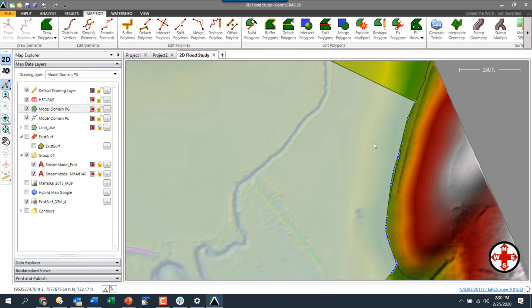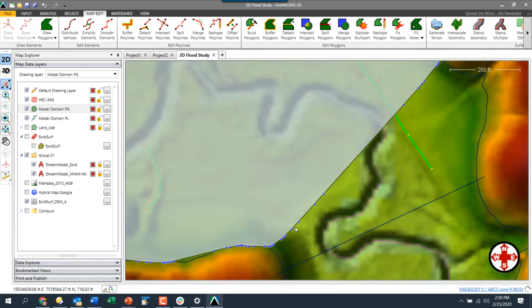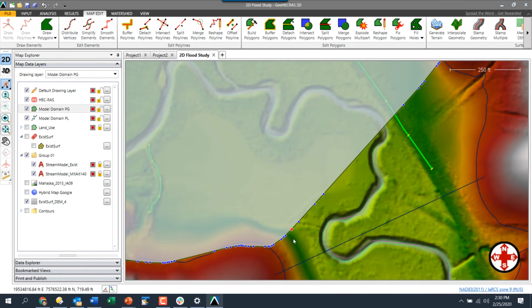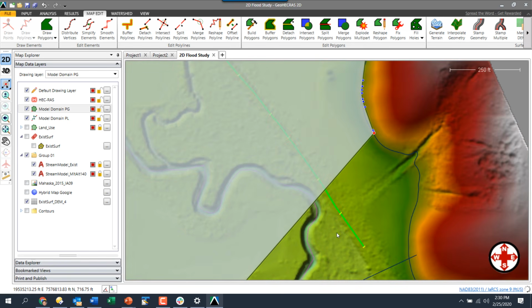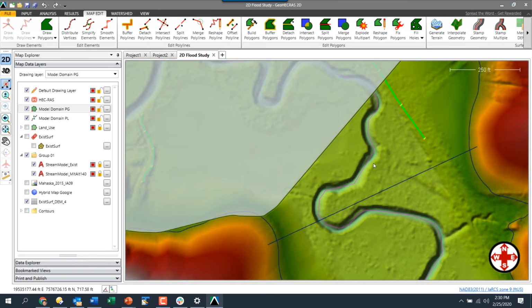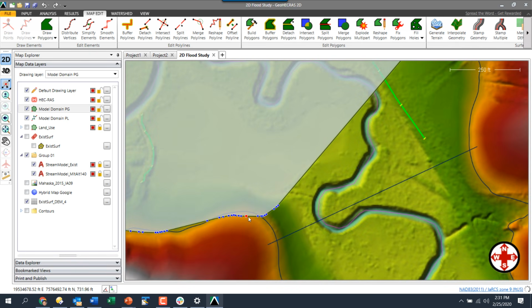There, okay, that one's cleaned up. Same thing along this boundary, come in here, grab one of them, hit the delete key, take it over there, and straighten that out. Oops, and we can undo, Control Z will undo. The same thing, we can come over here, figure out we're going to start deleting there, and trim that out. There we go, and can grab that point, pull it further down.